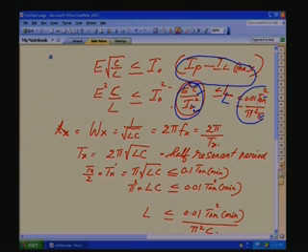Okay. Now, what do we want to do? The purpose of introducing this force commutation is what we want for a PWM operation of the thyristor, so that we can have unity power factor from the mains. At the same time the converter should be able to work in the 4-quadrant region, so that power flow can be from the input to the load, and from load to the mains. So, what is the basic configuration for a 4-quadrant converter?